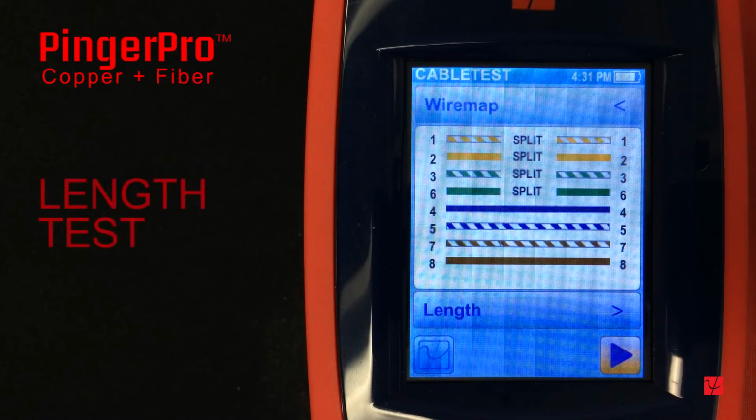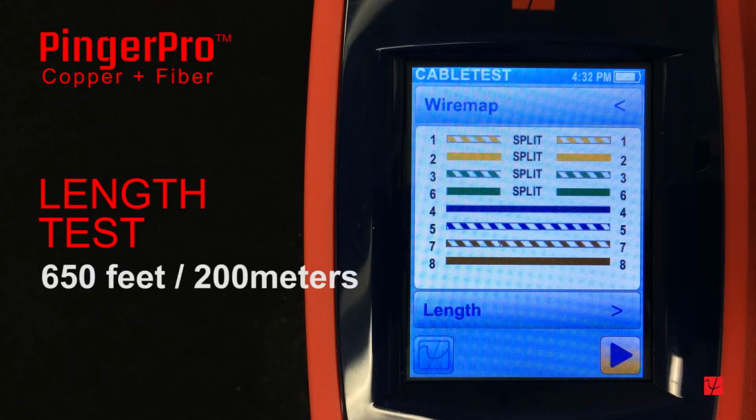A length test is used to electrically measure the length of a cable or identify an open or short fault and give the distance to the fault. This test is run from just one end of the cable and can be run from either end. The PingerPro will measure cable lengths up to 650 feet or about 200 meters.